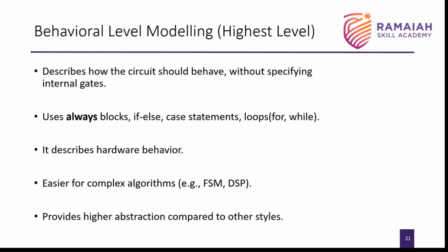I hope you understood data flow modeling. Now, behavioral modeling tells you how the circuit behaves. We are not aware of what goes on internally within the circuit. We don't know what functionality it is doing. We only know that if it is an AND gate, it should be A and B. That is, if it is 1, 1, then the output is high. Otherwise, it is 0. That is how the truth table of an AND gate works, right? That is what we know about the circuit. So how do we develop that logic using behavioral level modeling? That is the major aim of behavioral level.